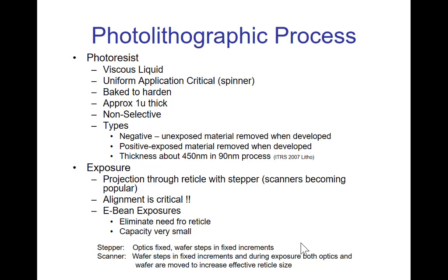So this photoresist material is just a material that when you put light to it, the part that is exposed to the light will have a change. Okay, so now the property is different. The exposed and the unexposed will have a different response. You can have photoresist materials that you expose, and then the exposed part will stay there and everything else can be dissolved. There's another type where the exposed area will be dissolved. Okay, so you have these two types. You can use either one.